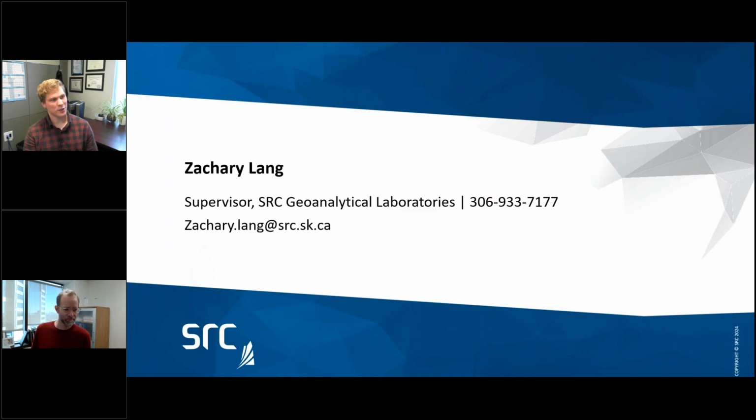If you get down to using DMS and they have a greater effect on your particle, how coarse are they, right? If they're coarse enough that they can have a distinct separation from the gangue in DMS, then that's good. Or if there's enough of them present, like I talked about in a particle depth separation, that's good. It really just depends on the specifics of the sulfides you're treating and the background mineralogy. That's a more specific question. I don't mind talking offline just because we only have a little bit of time left.